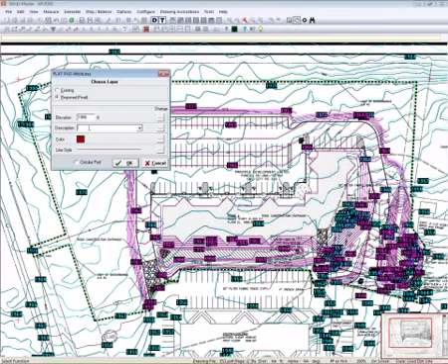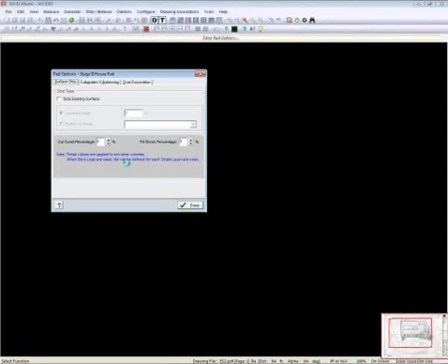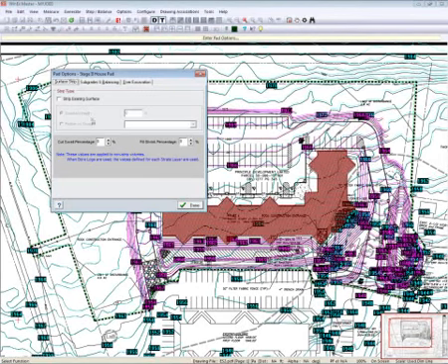And we'll name it, and then I'm just going to call this Stage 2 housing pad. Again, you can change the color. I'll hit OK. At this point, we could take another strip under the surface of the pad. You remember we took a 6-inch off the entire site? In our software, if we were to take another 2 inches just under the pad, it would be cumulative under the pad, so we'd have 8 inches. But I'm going to go right to subgrades and balancing.